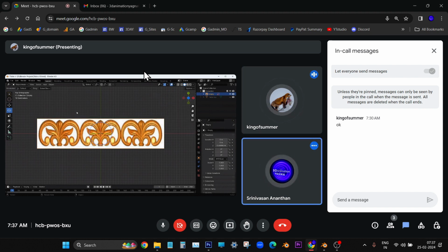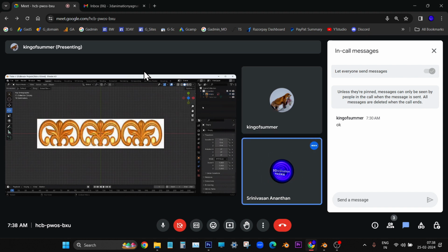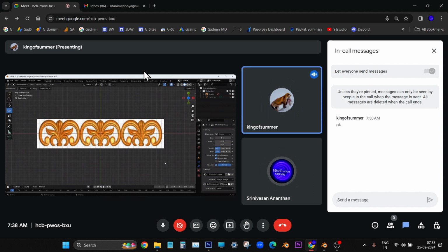Even the translation movement also 0. All Z is not 0 actually. No scale, that one is it. Fine. Now go to the properties panel, right side down. Yeah, select that one. Now, do you see opacity? Switch on the opacity. Now make it 0.2.